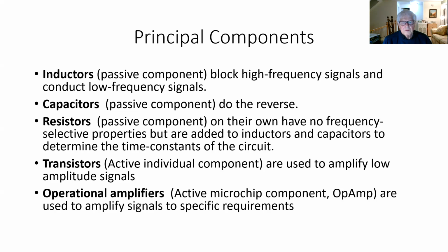Resistors are not reactive, so it's a passive component. Non-reactive, so they don't contribute much to the passage of a frequency or filtering of a frequency. But together with a capacitor or an inductor, they create a time constant which allows you to select a frequency range.